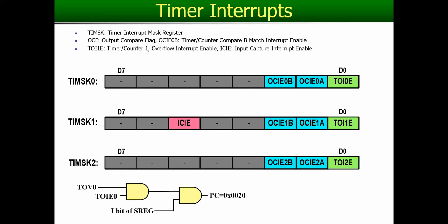Okay, and that's how we implemented different modes of the timers. In normal mode we go to 255 and then we get rollover. We get overflow, and in the output compare match we just put a value in that register, and that's when we are rolled over. Well, the term for that is not an overflow. It's kind of like a reset.